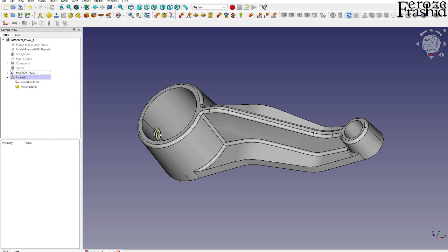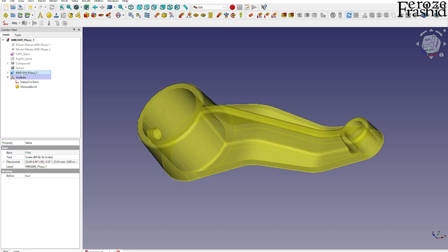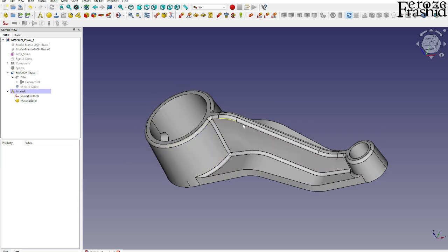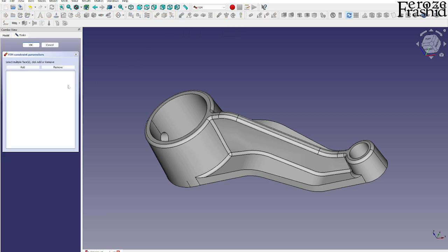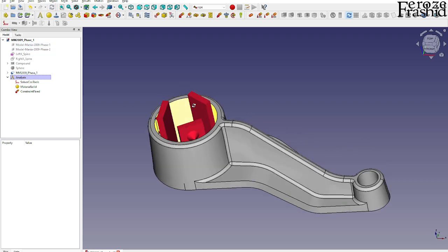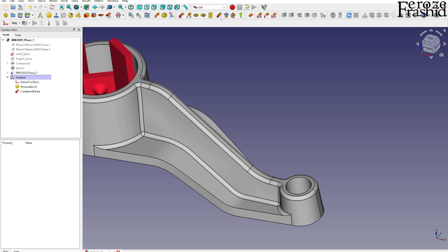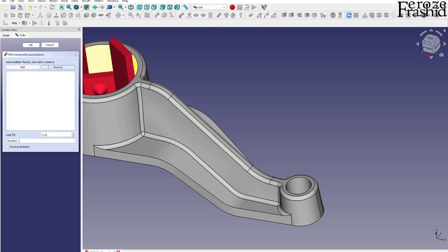this. Okay, on this one though, I want to actually go ahead and hide these threads. I don't know if it's a good idea to leave them on during our FEM analysis. And I'm not sure these fillets are helping in our FEM analysis. We'll see. So this is where we constrained this face. So it's fixed support right there, right? And then we come to apply load on here. So the load button is here, constraint force.